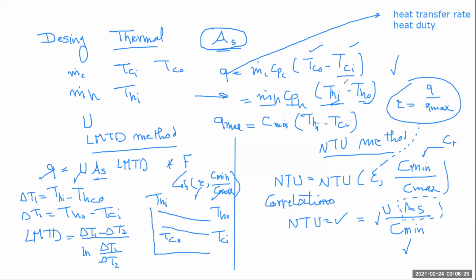And then they started using the duplex stainless steel, which is stainless steel covering both sides of the tubes. It is expensive. And then they had to use titanium for the high temperature applications, especially that with time and advancement in the knowledge, they tend to increase the temperature of the seawater that they heat. So titanium becomes a very good choice.